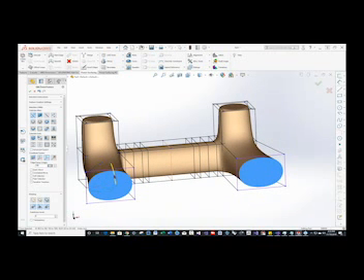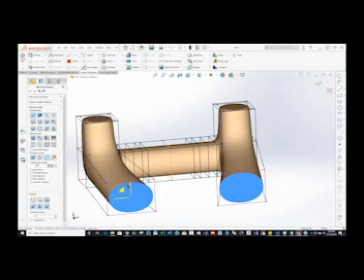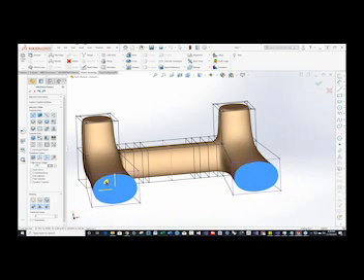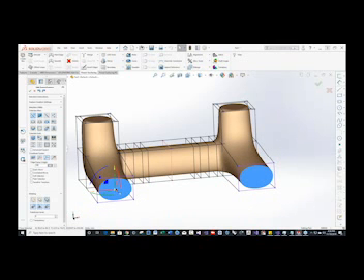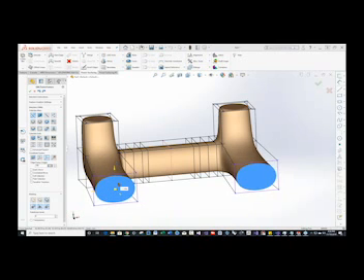You have the rotation capabilities with these rounded arrows, which is pretty standard. You also have the ability to move in a plane. As I hold over this one, that says I'm moving in the X and Y plane. And this one is scaling in the X and Y plane, so you can scale up or down. The middle one actually scales in the X, Y, and Z plane, which won't have any different effect because there's no Z component in this one.